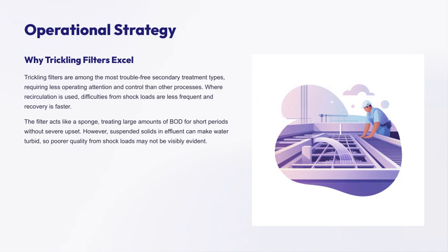Unlike some other treatment processes, they require less ongoing attention and control, making them more manageable overall. When recirculation is involved, they tend to handle shock loads better, with fewer difficulties and quicker recovery times. Think of the filter like a sponge. It soaks up and treats large amounts of BOD quickly, without causing severe upset to the system.